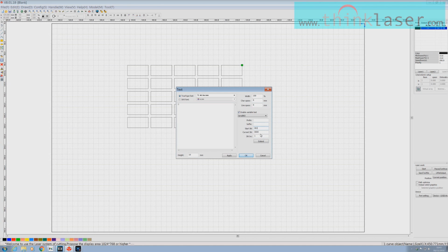Then the current serial number, we'll start that at 001 as well. Now make sure you don't fall into the trap of making that 1 for your current serial number, because that will force the same situation where it will only go to 9 and then roll over. 001. The serial number increment, well, yeah, we're happy to leave that at 1. And then we're going to the extend.